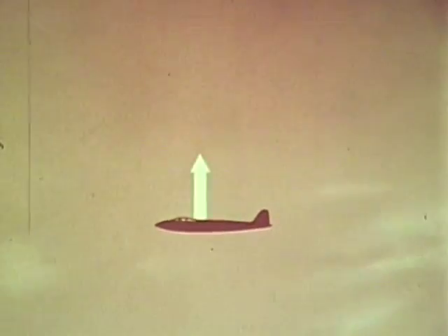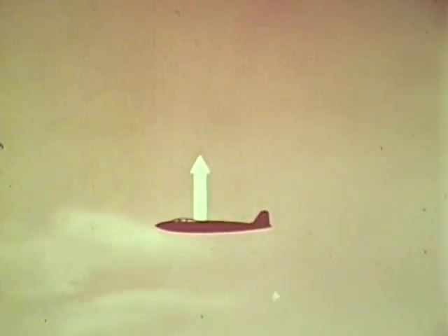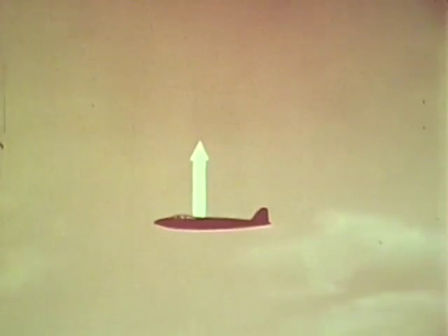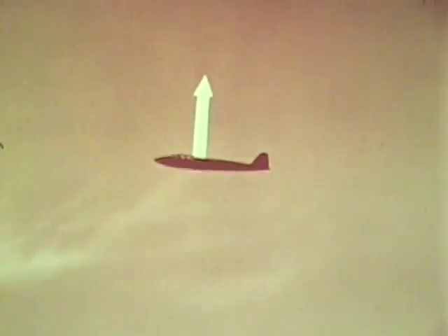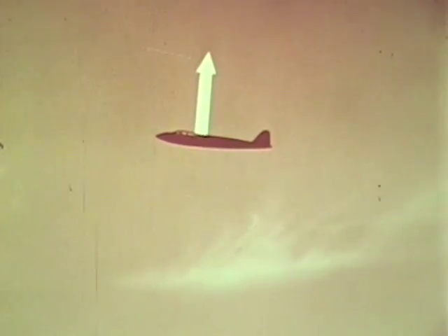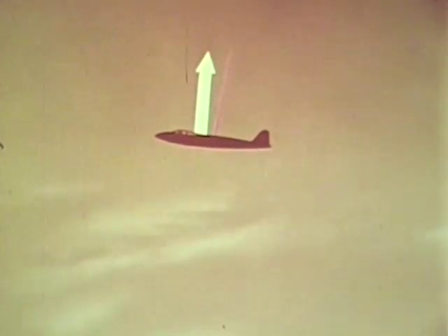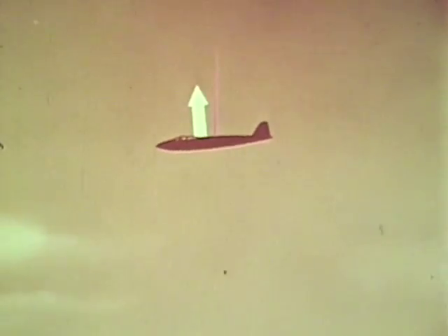The shock stall can also cause instability. For instance, changes in fore and aft trim. First, lift increases slightly just below the shock stall. This causes the aircraft to gain height, that is, assuming the pilot takes no correcting action. Next, at the shock stall, the sudden loss of lift puts it nose down.